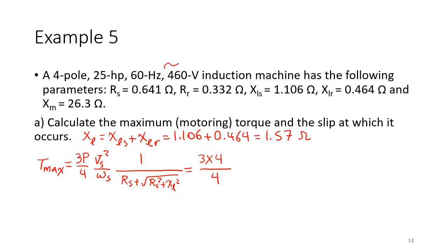Here this is line to line voltage, but we need line to neutral voltage here. So multiply by 460 over root of 3. I will be really disappointed if you make such a mistake in your exam.